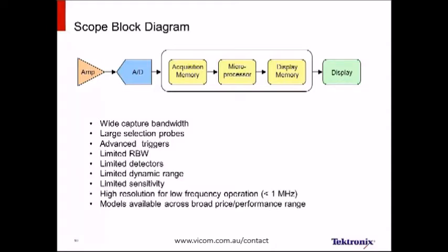Models are available over a broad price versus performance range, and you can even get into some Tektronix Windows scopes that have spectrum analyzer applications that can run on top of them. It can directly turn the oscilloscope into a spectrum analyzer. But even when we do that, we can't actually fix the insensitivity on the front end of the oscilloscope.